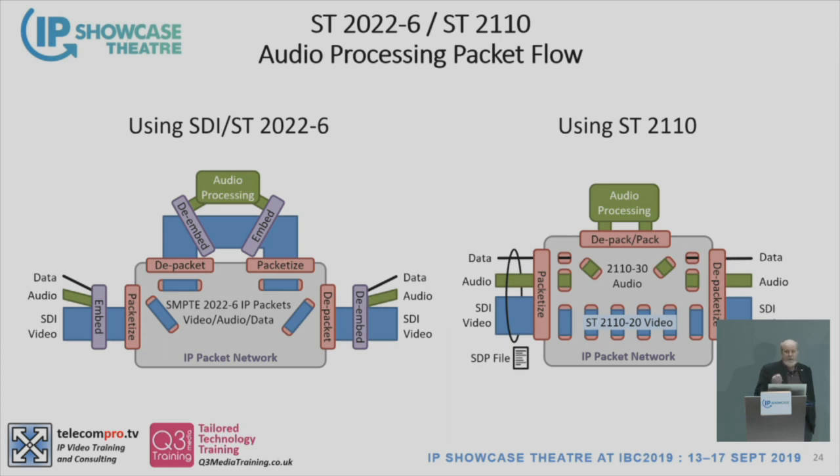With the audio stream, all you need is an audio receiver that can accept that bandwidth, generate it, and process it, and create another new stream going out that allows you to have just that amount of bandwidth. So instead of here, where I have an audio processing device that only needs to handle maybe 3-4 megabits worth of traffic, what I need here is an interface that has a bandwidth of 1.5 gigabits or 3 gigabits, if that's the type of video signal I'm using.